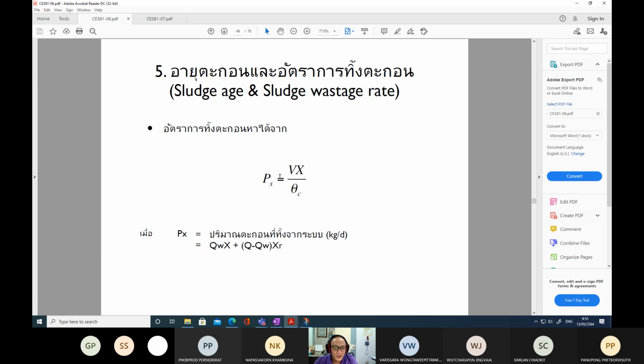So we have to handle this sludge, I mean, the sludge generated from the wastewater treatment plant. Similar to the water treatment plant, we use coagulation and flocculation, followed by sedimentation. So sludge drained from the bottom of the sedimentation basins, we also have to handle, but the characteristics of the sludge from water treatment are totally different from the sludge produced from the biological wastewater treatment process.